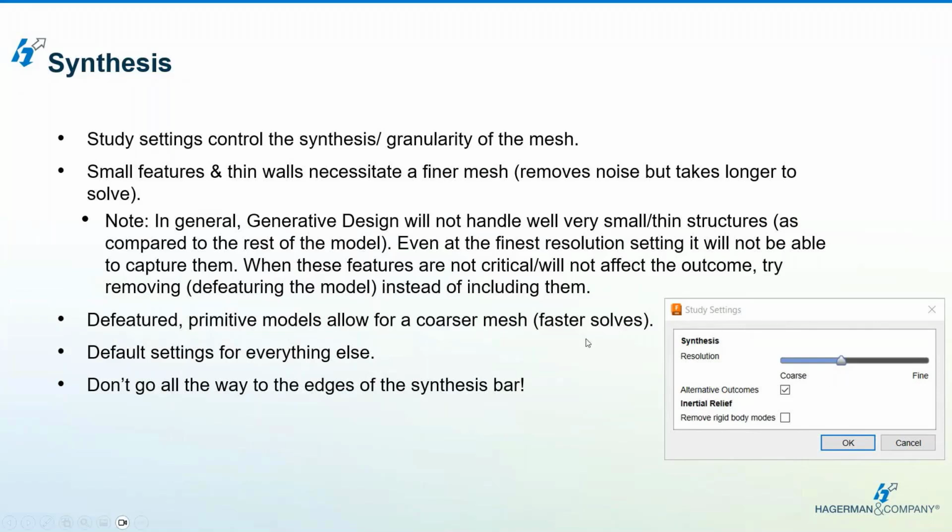Once we do it, the fine synthesis is going to take a little bit longer for it to have the outcomes, because it's trying to really refine the design at the end. Okay, so that's where we have the settings in there, and I would just leave it as default if you're just trying this out. But then eventually, if you get more advanced inside of generative design, you can start playing around with this resolution and everything. Or if you need something fully optimized, you can then set the resolution to fine.